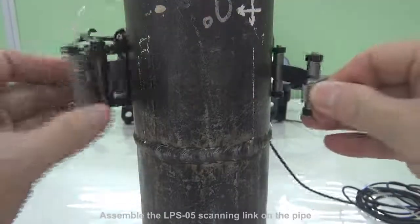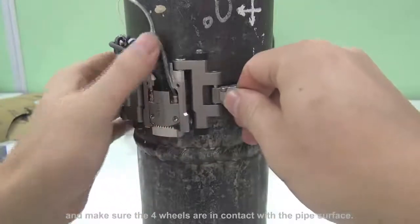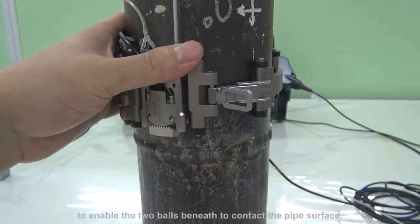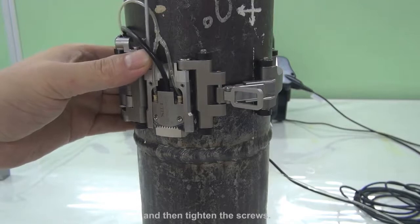Assemble the LPS 05 scanning link on the pipe and make sure the 4 wheels are in contact with the pipe surface. Press down the probe holder to enable the 2 bolts beneath to contact the pipe surface, and then tighten the screws.